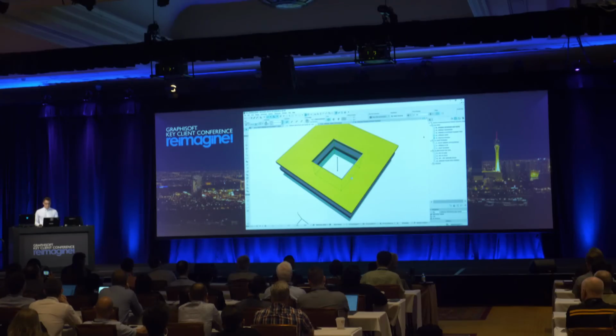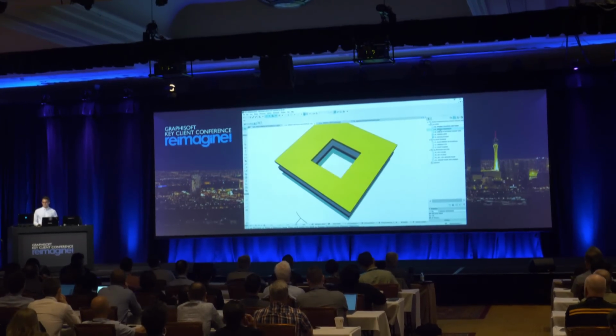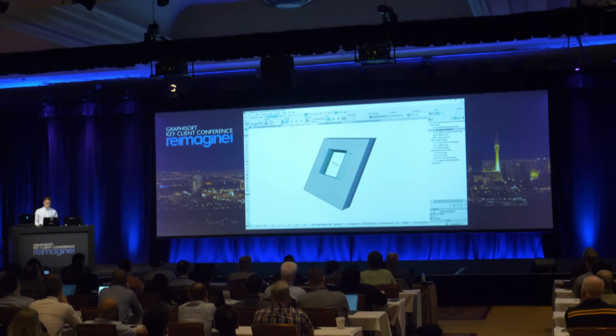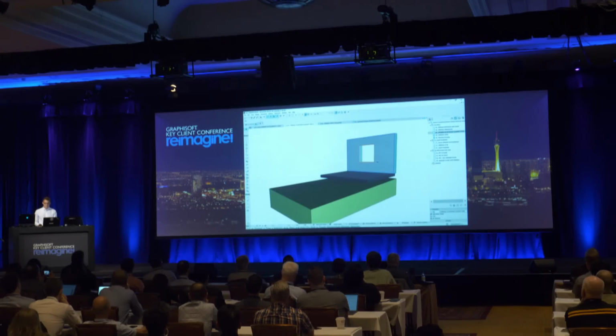The opening tool was created with the IFC definition in mind, meaning that an opening belongs to one element, but it can be linked to multiple elements at the same time. So see, this is one opening cutting through all layers at once. What else can we do with this particular opening? An opening can be aligned with the surface, or it can cut through elements vertically and horizontally. And it can also have a custom angle, which gives us flexibility in geometry and design.